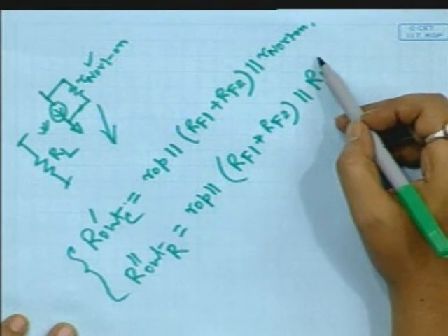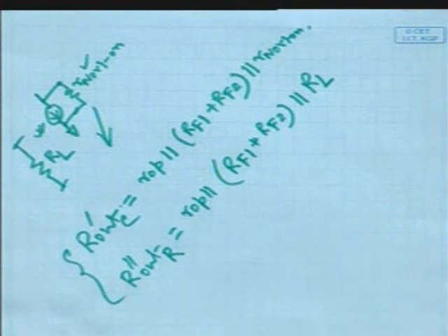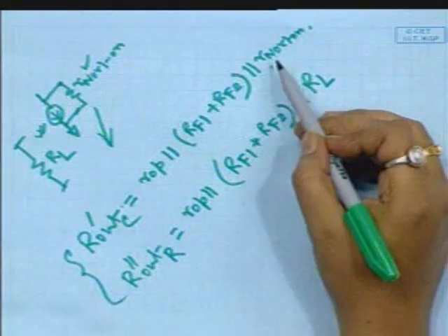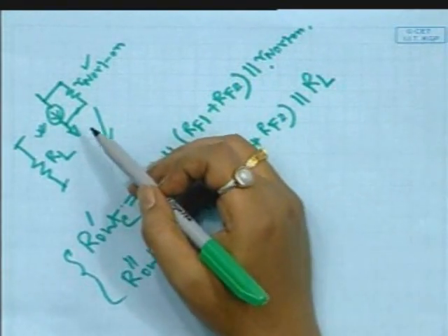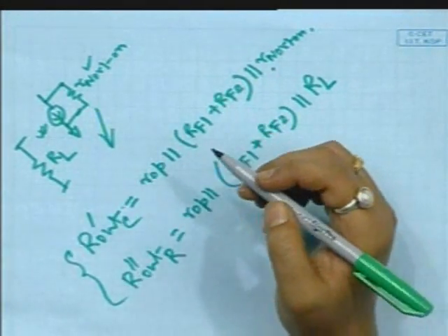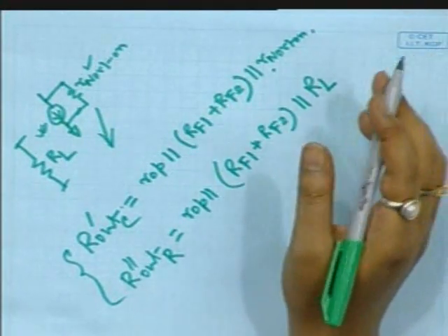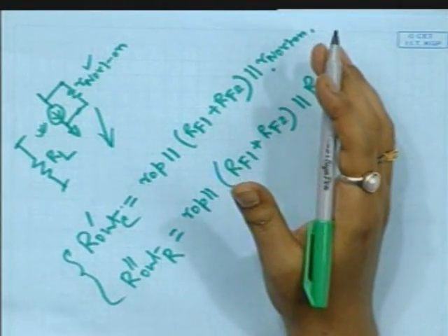From the analysis and by inserting typical values, you can observe that for the resistive load, the output pole P2 will be located at a much higher frequency than the pole for the current source load. But for initial analysis, the resistive load is better. When you are going to define a system, and inside the system the LDO comes as a component, at that time it should be modeled as a current sink load.